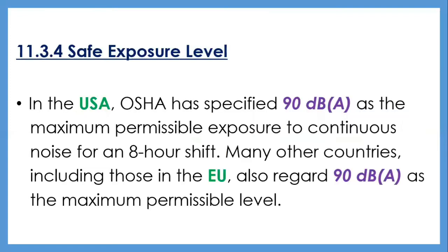And the next key area that we're going to be discussing is safe exposure level. In the USA, OSHA, the Occupational Safety and Health Administration, has specified 90 dBA as the maximum permissible exposure to continuous noise for an 8-hour shift. Many other countries, including those in Europe, also regard 90 dBA as the maximum permissible level.